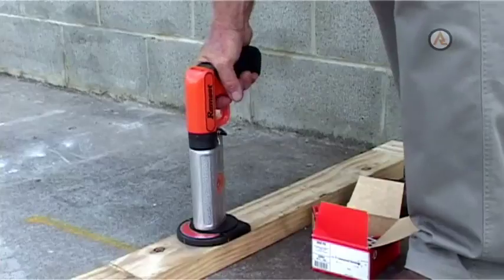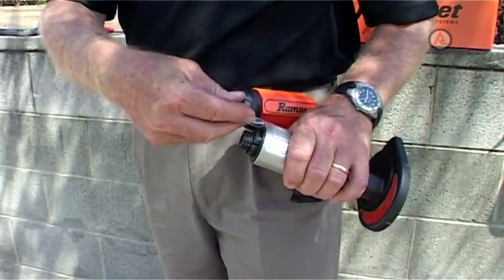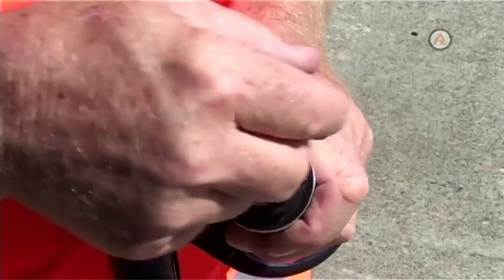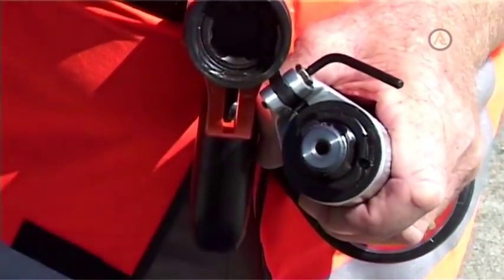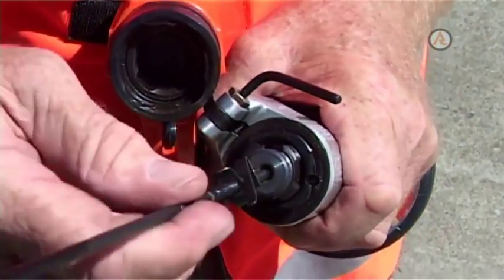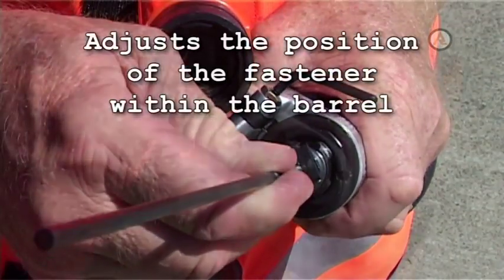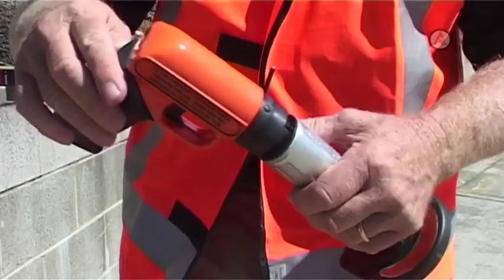In this high-velocity tool, the spent power load must be manually removed. If required, the strength of a power load can be reduced in a high-velocity tool by using the power positioning rod. The power positioning rod is used to adjust the position of the fastener within the barrel. The power is reduced the further down the barrel the pin is positioned.